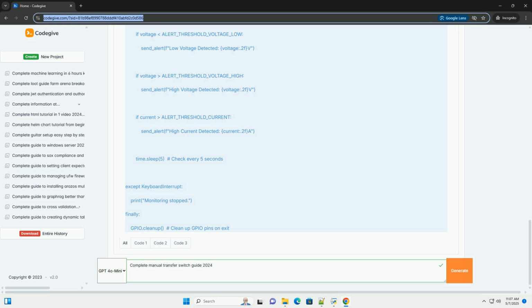1. Planning. Turn off the main breaker to isolate the utility grid. Plan the wiring route from the transfer switch to the generator inlet box. Mark the circuits you intend to power with the generator. Review the transfer switch manufacturer's instructions carefully. 2. Mounting.